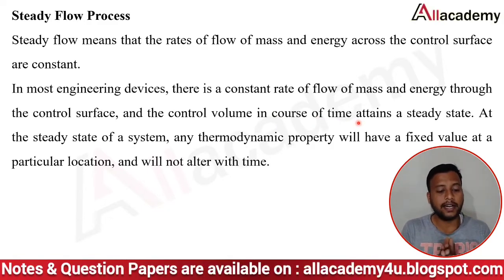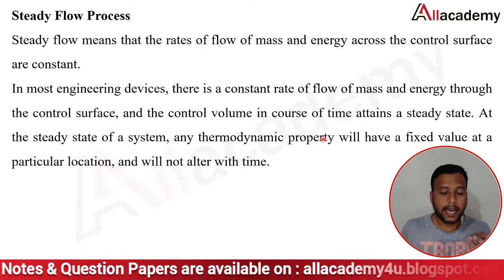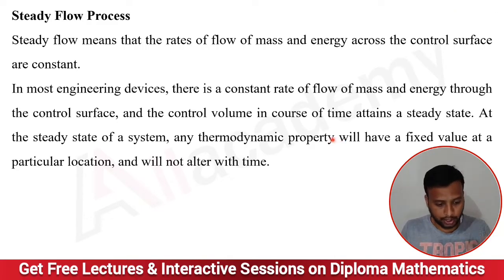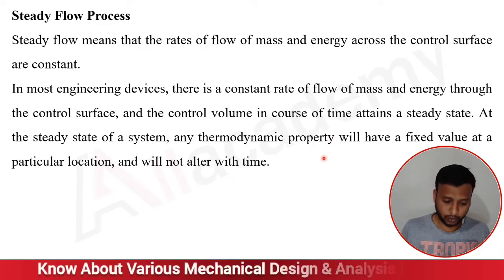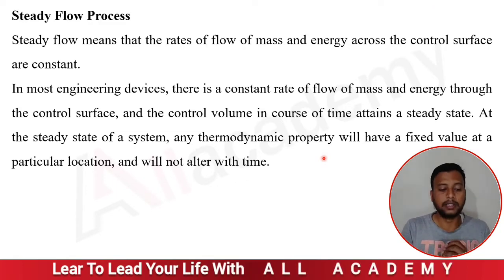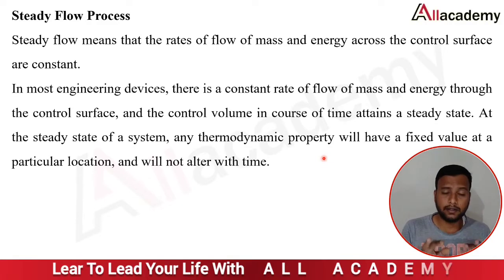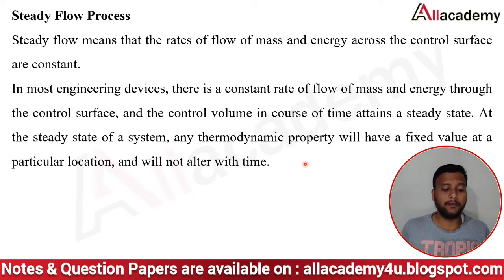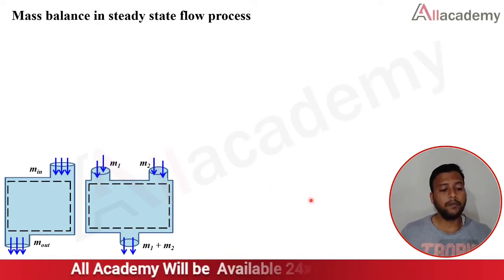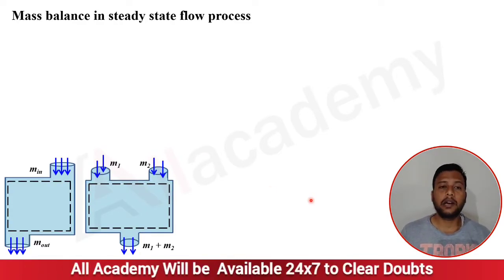Very important here: steady state means that whatever flow of mass and energy takes place through this control surface, the control volume attains the steady state in the course of time. In the steady state condition of a system, any thermodynamic property will have a fixed value at a particular location and will not alter with respect to time. Whatever thermodynamic properties we have identified in this control volume will have a fixed value at that location and will not alter with time.